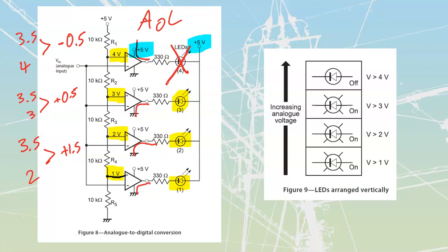What we have over here is just a very low scale that's telling us, basically a volt at a time, what we have on our system itself. It's got a relatively poor ability to tell exactly where we are. We were at 3.5 volts. If we wanted to increase how much we could tell, what we would have to do is add in more op amps, and increase the number of sections inside of my voltage divider. This is referred to as increasing the resolution, or how fine of a component that we can look at inside of these.